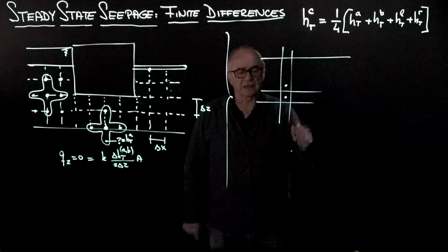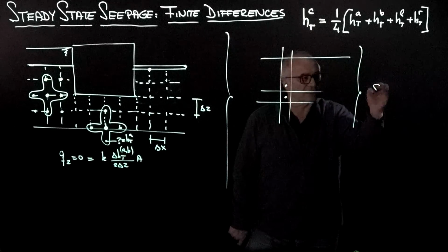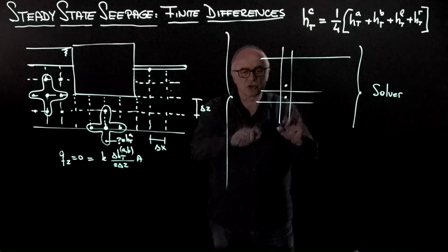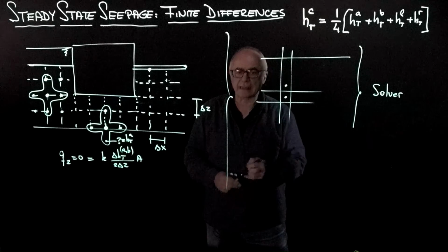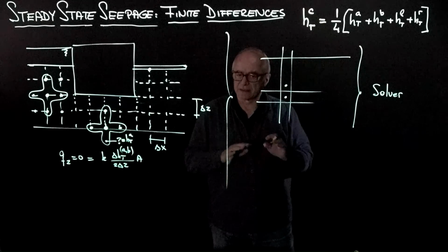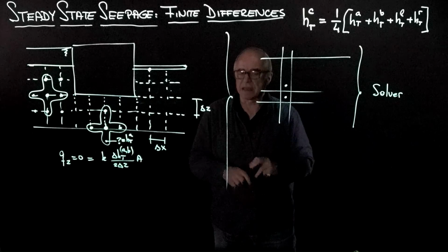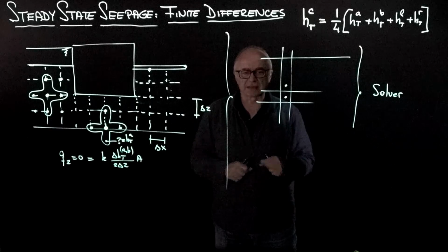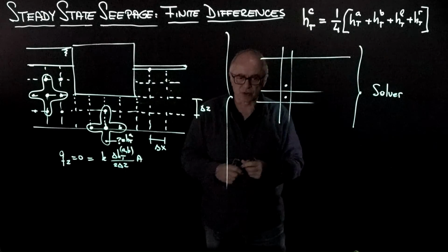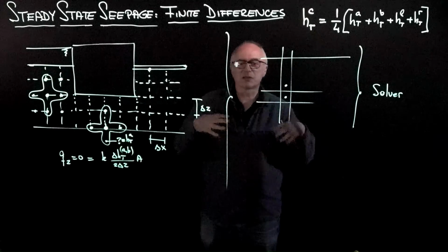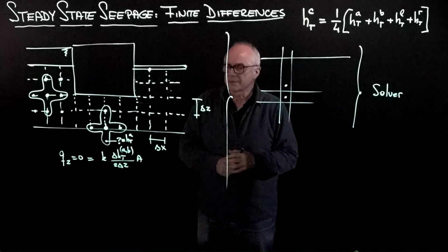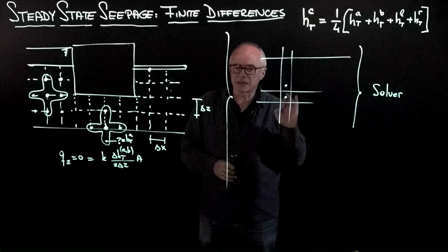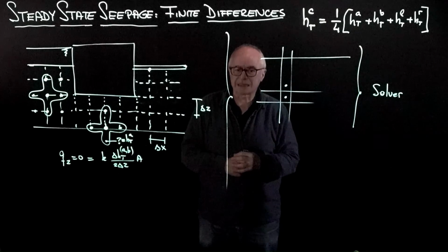You know the boundaries, and you use the Excel solver, and it will rapidly iterate to converge to the solution. I know that this is a very trivialized introduction. There are many numerical improvements that can be done with the proper kernels at boundaries, with the proper algorithms to solve this and to bring this not only to 2D but also to 3D. But this is a very simple and valuable introduction to the problem of a steady-state seepage solved numerically.